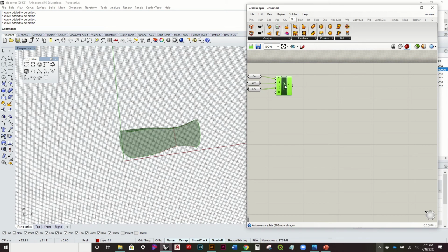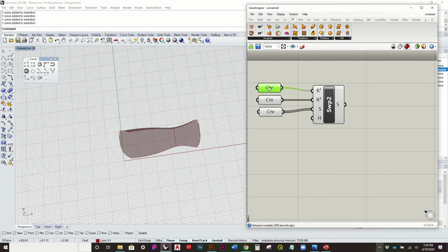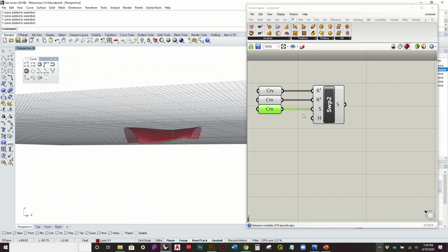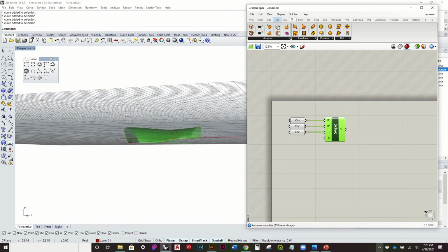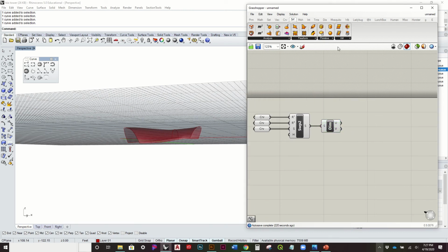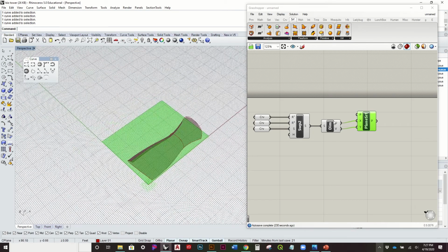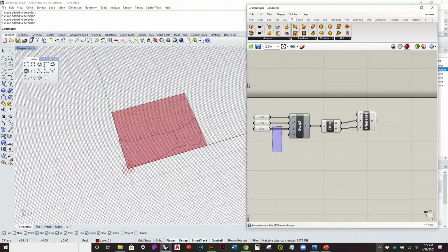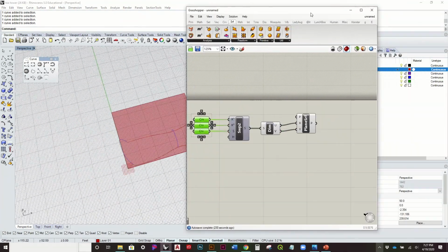And so we want to follow some very specific parameters, because at the end we're going to morph what our planar surface is onto this surface. So we'll take this surface now and find the dimensions. So we'll get our u and our v values, and we'll use those to create a planar surface. So basically u means x and v means y. And so you can think of this new planar surface that's been created as basically an unrolled or flattened version of that. So I'm just going to turn off some of these things.